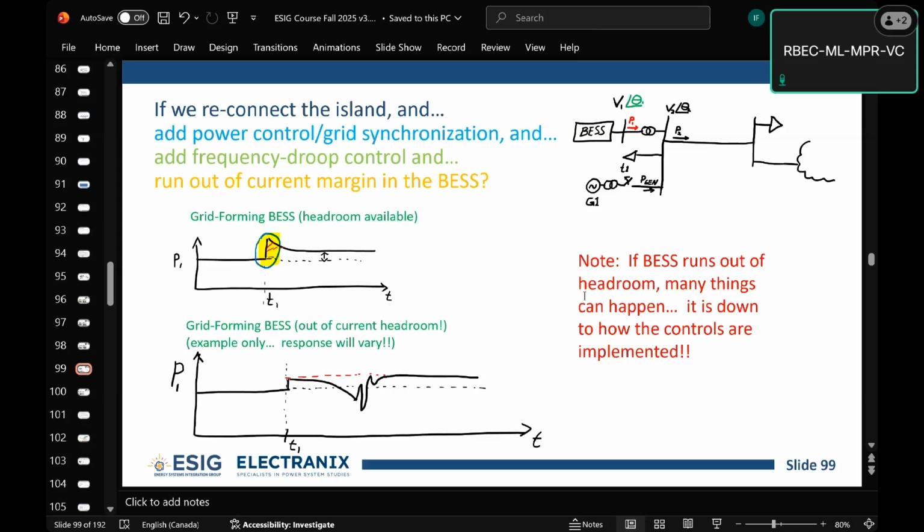Yeah, and I think you can take a balanced approach to that. I don't recommend that most utilities use HECO's grid forming tests, at least not all of them, because those can actually influence the optimal behavior in stronger systems. So most utilities, you want to have tests for grid forming that are relatively representative of what's going to actually happen in your system so that those systems can be tuned reasonably for your system.